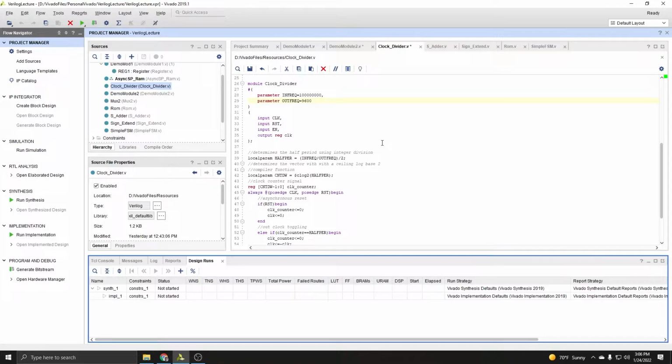Now I know having a bunch of files is something that a lot of people aren't used to because they're used to writing C code where you can just put everything you want into one file and import that one file. In Verilog, it's just easier and better for everybody, including yourself, to have one module per file. So if you have a bunch of modules, it's better off having 20 files and 20 modules than one file and 20 modules. It'll just be so much of a pain to try to debug those.